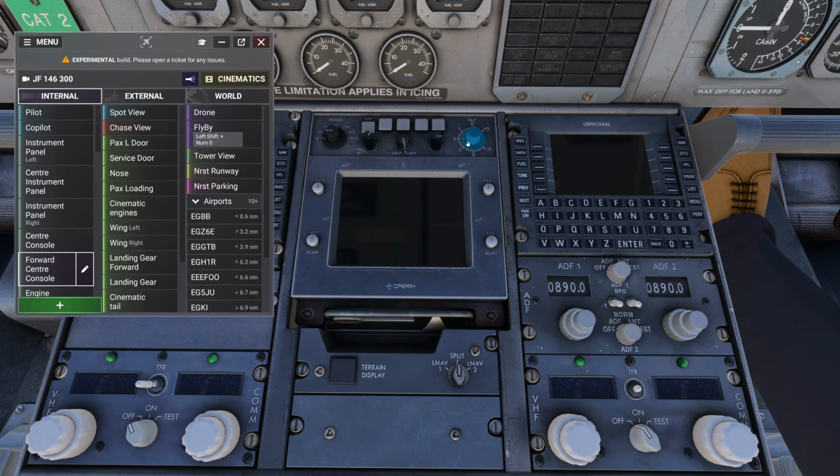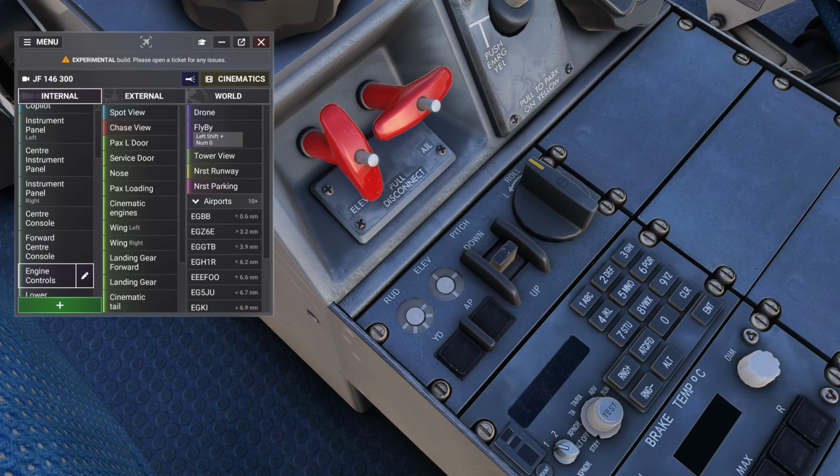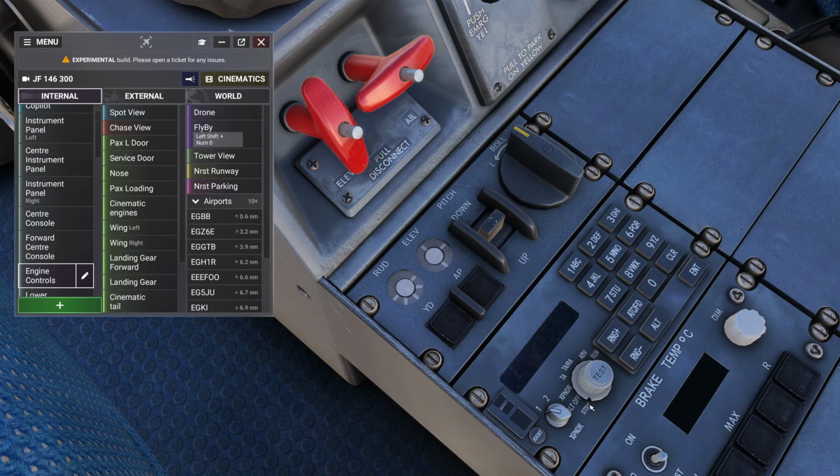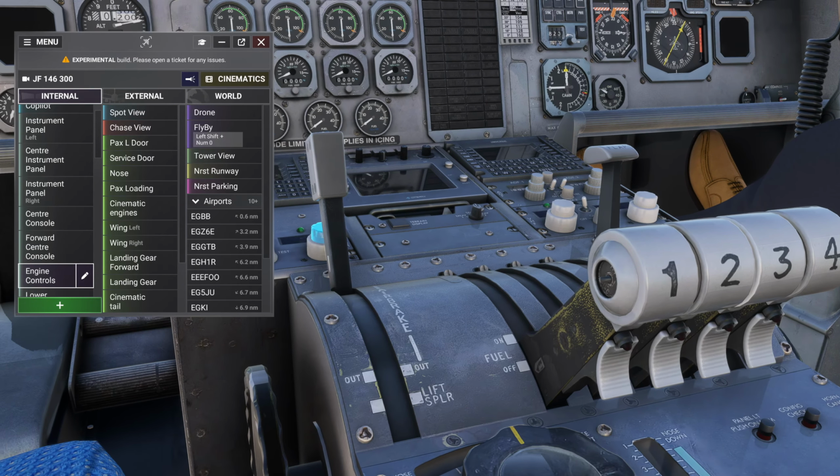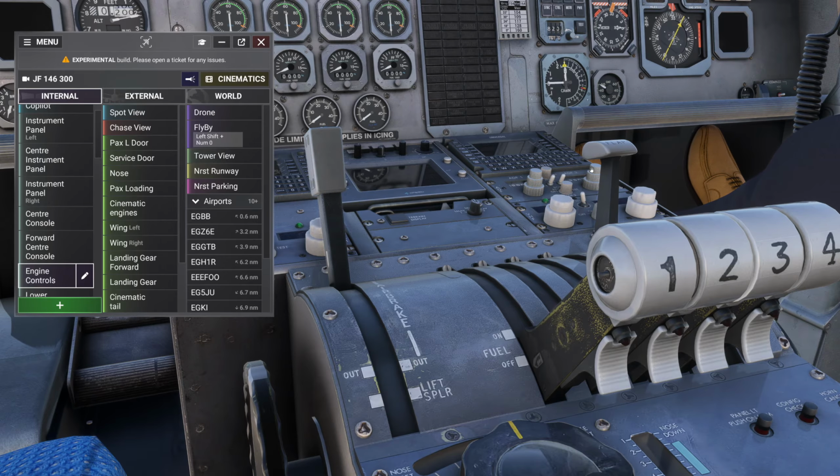Radar is off and I will set the tilt to 15 up. Checked. Perfect. That's done. All right, let's move on to the next step. The transponder should be set to standby. Let me know once you've got that sorted and we'll keep going. And transponder is set to standby. Checked. Awesome. Next up, let's ensure that the speed brakes and flaps are retracted and up. Once you've got those set, just give me a heads up and we'll proceed further. They are retracted and up.